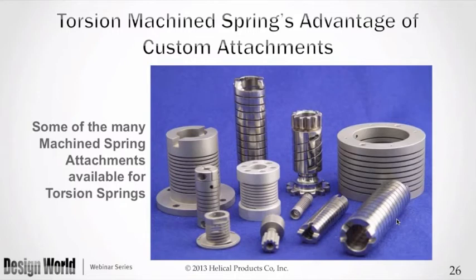But the others there have all kinds of other ways of getting hold of torsional springs. We've got gears, splines. There are holes in the ends of these springs. The big spring on your right is a typical aircraft torsional spring. You can see the small holes. That's used to hold the spring in place, and the torque is applied then by the two holes that are 180 degrees from each other.